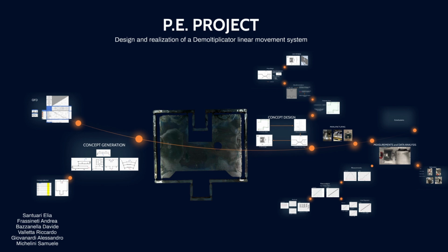To optimize the process, first it was necessary to deconstruct the problem in subunits and come up with specific solutions. These then were grouped into 5 concepts. Using the belief map, the choice fell on the symmetric double lever, which can be seen in the center of the presentation. After picking it, the concept needed to be designed, finding K, the length of the parts, and the dimensions of the hinges, and simulated to ensure it worked properly.